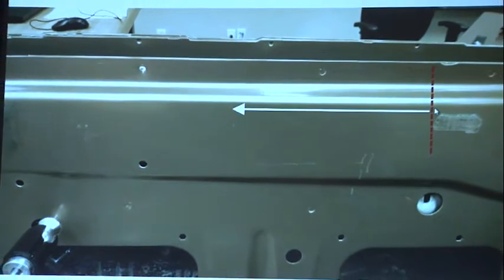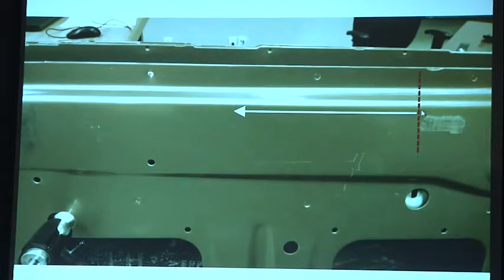Now to fix this, we'll just add one more scan pass, but we'll add it with a proper scanning direction, which means that the laser line will wrap around the fillet. So it will prevent having a point density that is too small, because the point density around that fillet will be defined by the point spacing on the laser line.